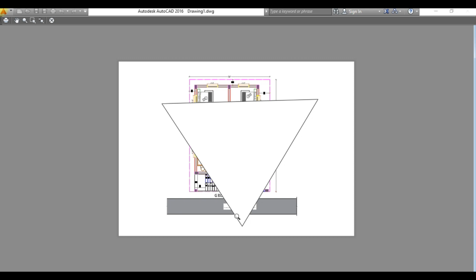See this existing boundary line we created with the help of the wipeout covering; this will display. Earlier, the third condition, plot but not display, would plot over there but not display. But when I switched it on, the coverings are displayed on my plot, meaning on my printing paper it will display.